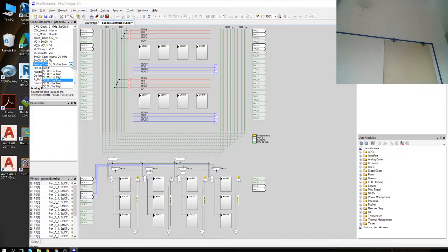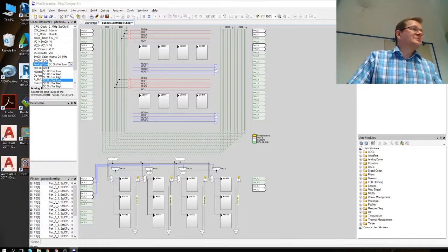When you have a continuous time amplifier, it consumes power all the time. But for the sleep time, you can turn analog power off, then turn it on again after the sleep. Just a small reminder that it requires a little bit of settling time when you turn it on and off. But it saves energy.